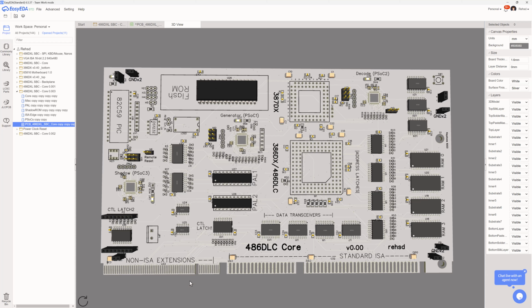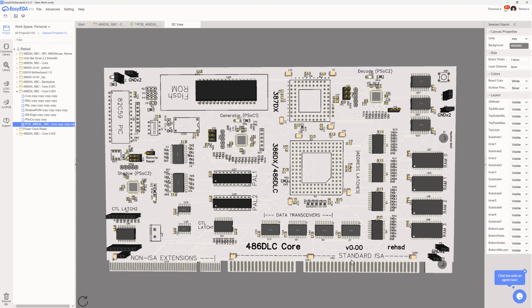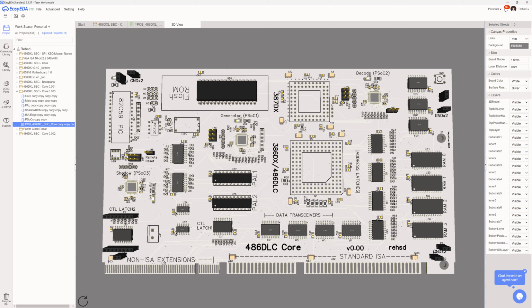I have to experiment with my actual slot connectors here and see how that's going to fit into the chassis and how many slots I'm going to be able to fit in one of those cases that I've been using, that open frame case. Again, I reduced my connections here from 0.254 millimeter to 0.2 millimeter for all my traces, and also pulled down the via size in the same manner. So I'm still at version 0, have not gotten to the point where I'm going to order this up yet,